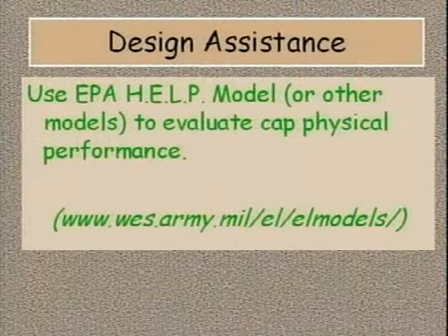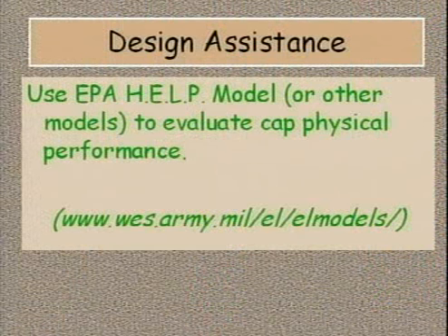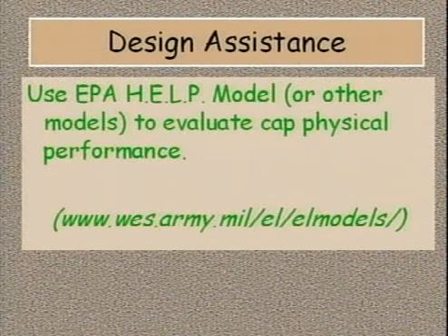The design of soil covers can be guided by a free computer model, the Hydraulic Evaluation of Landfill Performance, or HELP model, that is available on the web. This was developed by the U.S. Army Corps of Engineers. But the HELP model only addresses the physical performance of a cover system with respect to water. It does not address the geochemistry of the leachate.